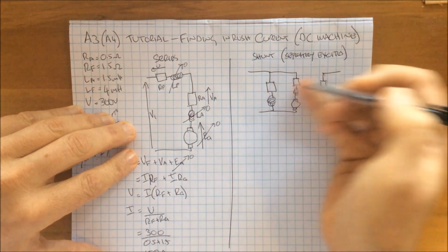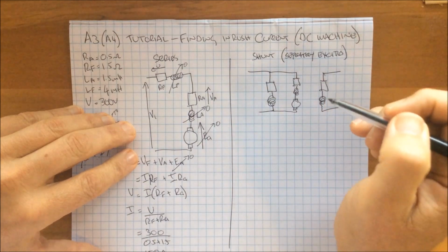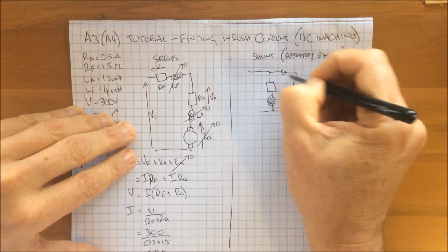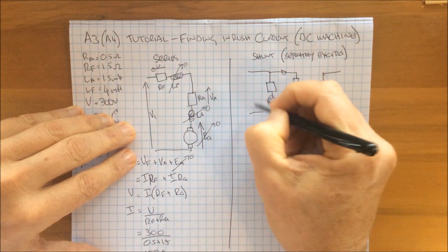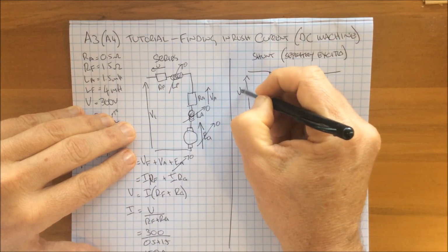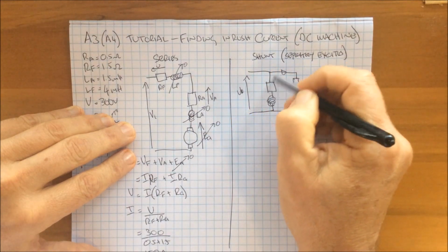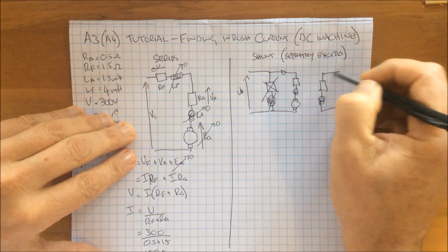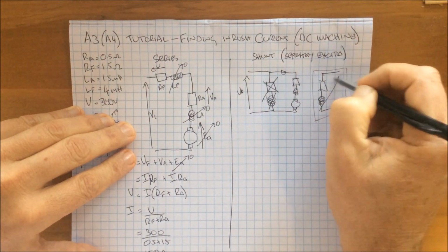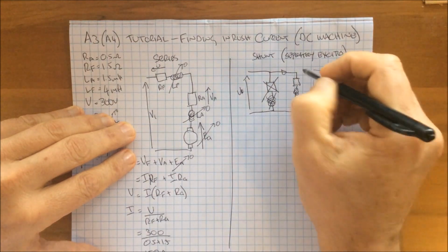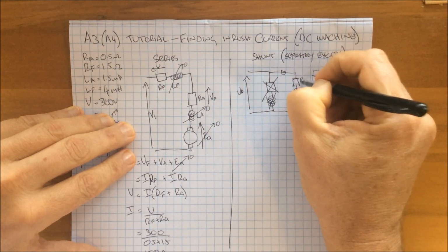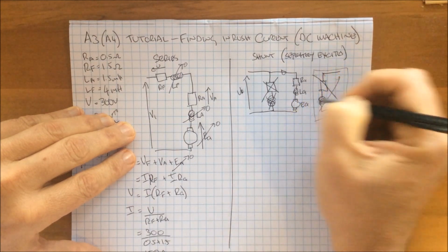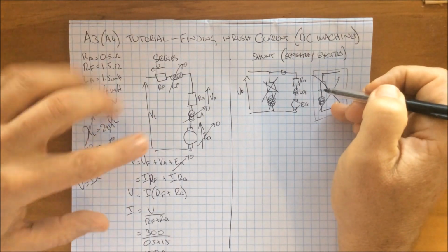Now, I do these two together because for the purposes of looking at inrush current, it doesn't matter. We're looking at the current down through here, through our armature. This is the current we're interested in. And we've got our voltage supply here. What's going on in the field doesn't matter. So we can just forget about all that. Similarly, how this is being excited over here doesn't matter. What we're interested in is our armature resistance, our armature reactance, and our back EMF. As I said over here,